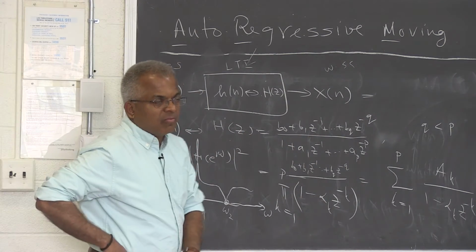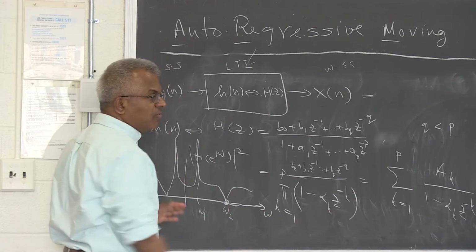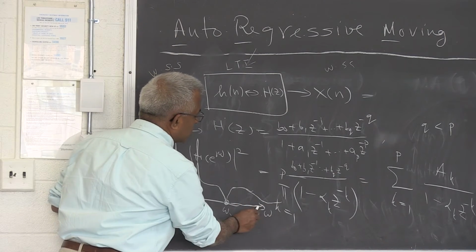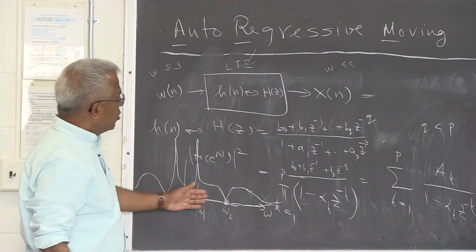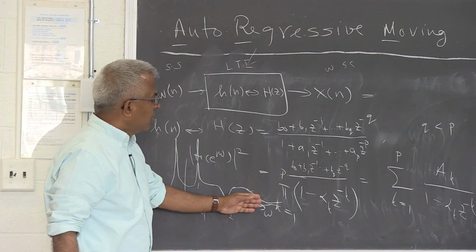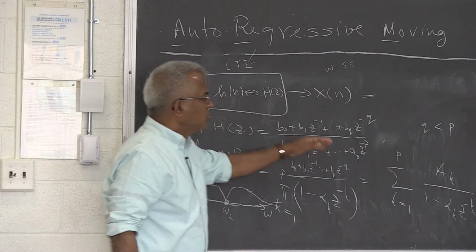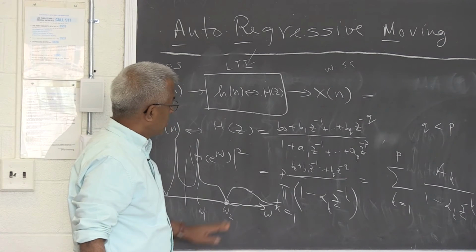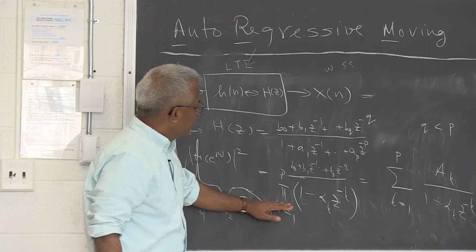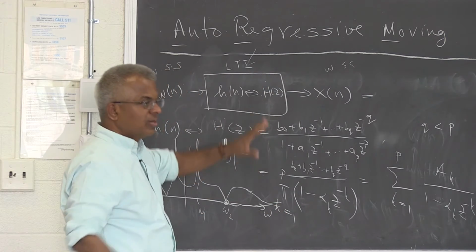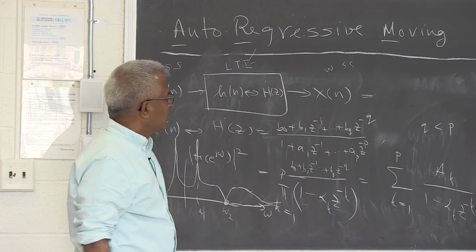So if you plot this patiently for all frequencies, and let's say later it goes like this. Then if you look at the system carefully, for example, this is saying that for large frequencies, this is going down. So this is already going to tell you the number of poles versus zeros, etc. So at large frequencies, the denominator must be taking over because the denominator is becoming larger, and it's driving to 0.